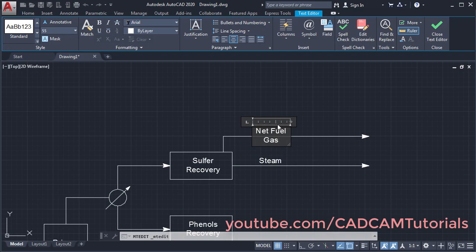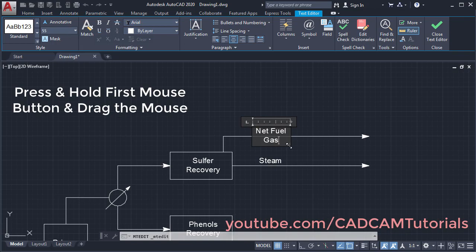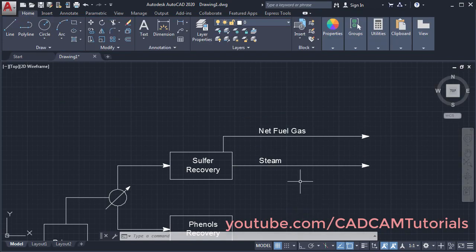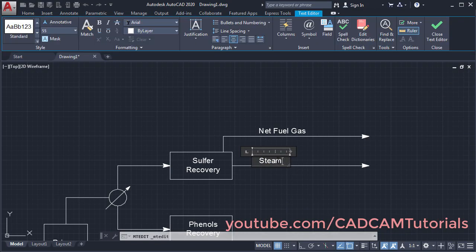Now here it automatically became two line text. To make it single line text, take your cursor on these inclined lines. Then it will show an arrow like this. Then press and hold the first mouse button and drag the mouse until it becomes single line text, release the mouse and click outside. Then double click Sulfur, click outside.